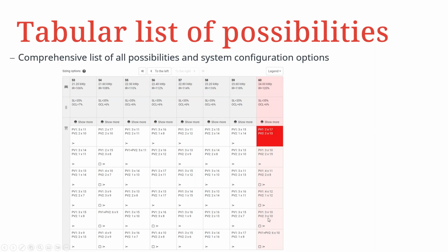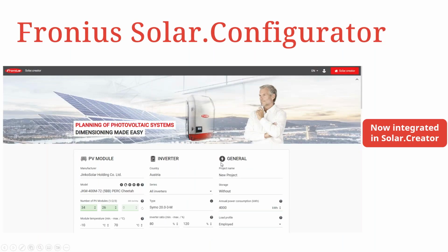So here, as we could see in the previous slide, we already have a preset value of 34 modules on MPPT1 and then 26 on MPPT2, as you can see. So this doesn't mean, so that you don't get it confused, that we're connecting 34 inverters to a particular string. This is basically what is going to the MPPT, okay?